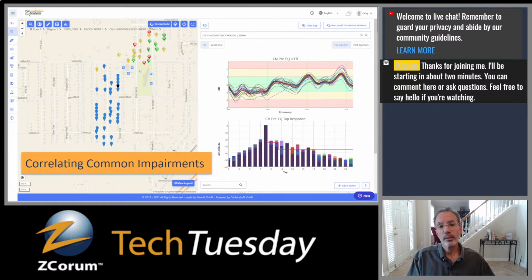Now, one of the things that you can do with a PNM tool, and this is a screenshot of our Pre-Equalization Analyzer tool, is you can pull up what's called a correlation group. What the application does is it looks at those in-channel frequency response lines, and it looks geographically at the devices that are close to each other, and then it says, you know what, all of these devices seem to have the same in-channel frequency response. And then it plots them on a map for you, and it shows you what those responses look like.